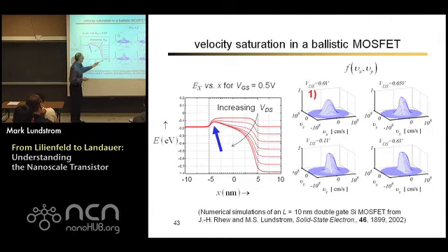The drain is also distributed in a Maxwellian velocity distribution. The negative velocity ones can get into the channel and come back here. The negative half of this came from the drain. So scattering did produce this equilibrium distribution, but it was scattering in the source that produced the positive half. It was scattering in the drain that produced the negative half.